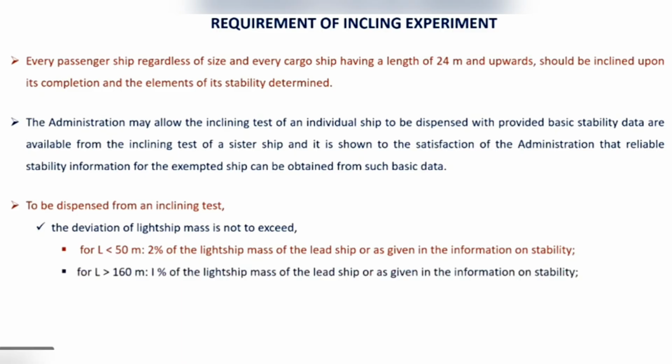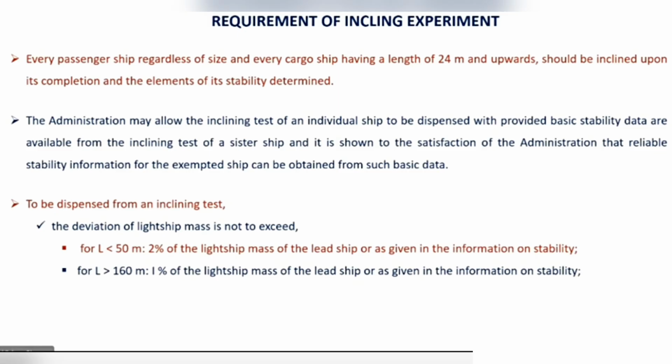Likewise, if the ship is greater than 160 meters, then this permissible deviation is further reduced to only 1% instead of 2%. And for lengths between 50 and 160, because you've catered to less than 50 and more than 160, there will be linear interpolation between these two values of 2% and 1%.